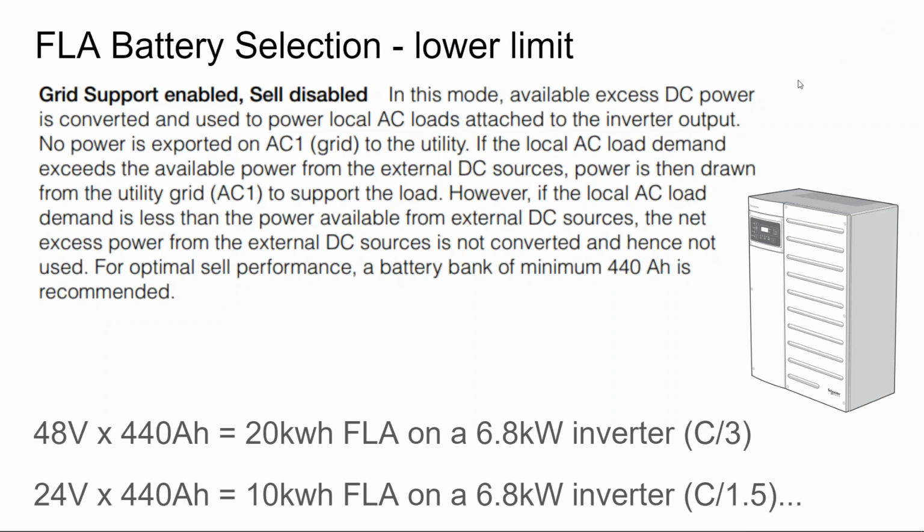So we're going to look at what is the minimum you can do. If you have a grid tie inverter, what's the minimum amount of batteries you have to add on it? This is a Schneider battery inverter. And the minimum battery kind of depends on your battery voltage. So there's not just amp hours, but also volts.